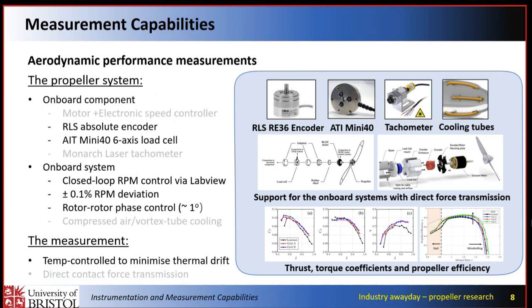Lastly, I'd like to just mention quickly that, as you've seen from the earlier nacelles, we also have some experience with temperature control. So we do incorporate different cooling systems in our rigs, depending on how large the rig is or how large our motor is. And this will enable us to monitor the thermal drift of the load cell, so our aerodynamic measurement is accurate, as well as it helps us to maintain the temperature of the motor so that we can do hot wire measurements later, which usually takes a long time.